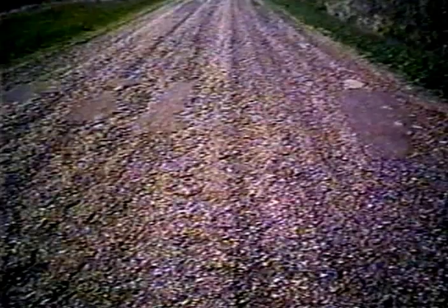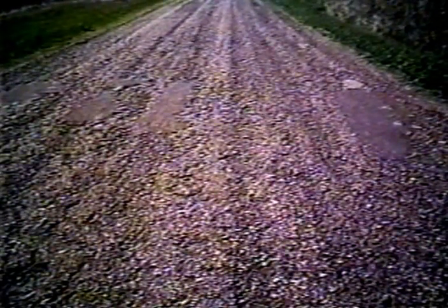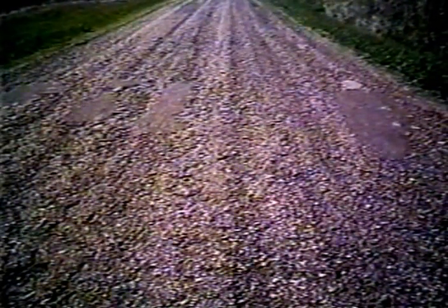This would be slight raveling. It deteriorates into what you might call moderate raveling, where you lose even more of the pavement surface. And frankly, you just see some of the large aggregate left there. That can continue into a more severe situation where you're losing a large portion of the pavement surface. And here's a final shot of a very severely raveled pavement that has gone to the extent that they've had to actually do some patching. It's rare that you see raveling go to this extent without some other kind of distress taking place, but it's a good example of raveling.